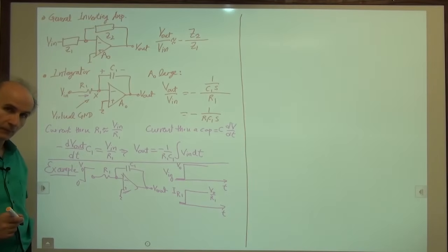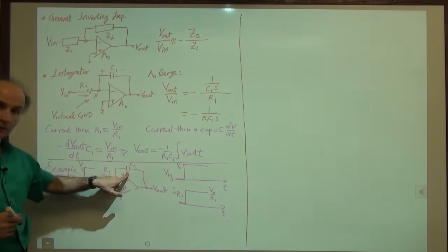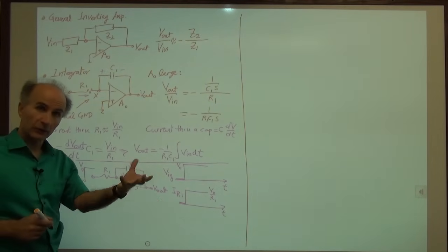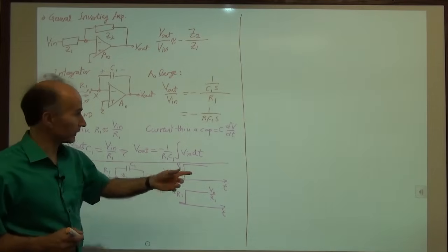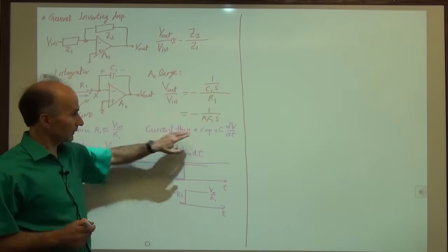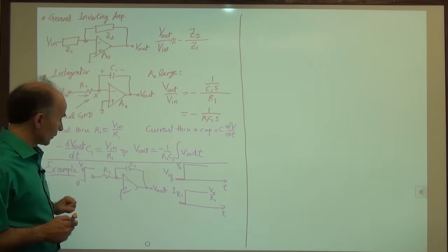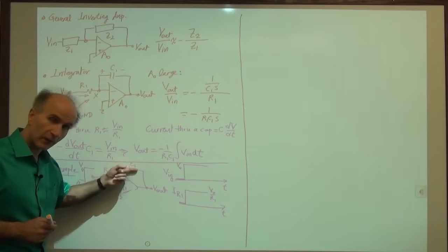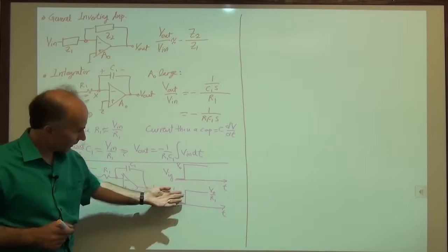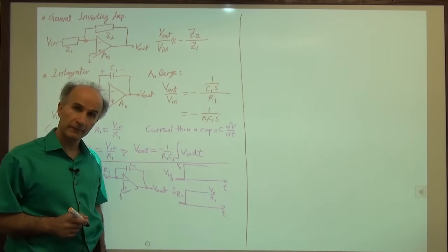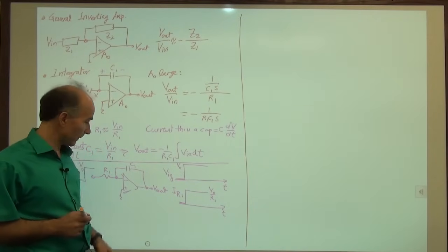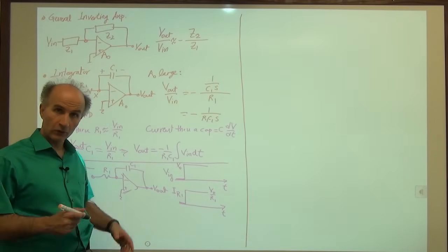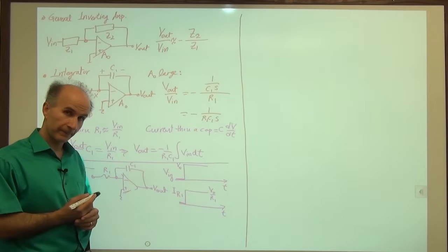All right. Now this capacitor receives this current. We know that if we give a current to a capacitor, the voltage across the capacitor is the integral of the current. Right? This voltage is the integral of this current divided by C. So this capacitor tries to integrate the current that's flowing from the resistor into it. And if we integrate a step function, what do we get? We are charging a capacitor with a constant current. So the voltage across the capacitor grows linearly with time.